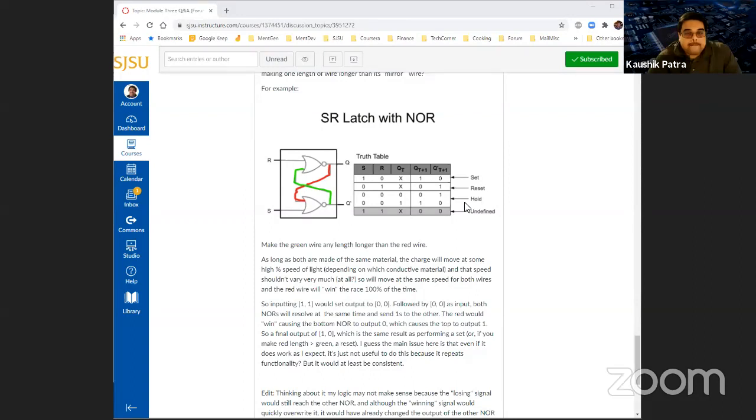Remember, the longer the wire you put on the chip, the harder it is to route the chip, because that chip has billions of wires and interconnects going around each other in a processor. So making long wires longer is sometimes really problematic.